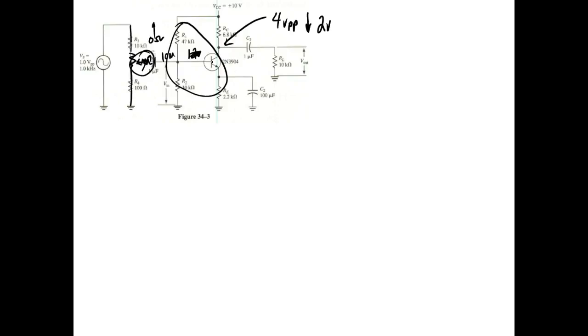But what I can do is adjust this till this drops down to 1/2. When that drops down to 1/2, I know that the rheostat equals the input impedance of the amplifier. Then what can I do? Well, I can turn it off and measure the value of my rheostat. So the value of my rheostat is going to equal the input impedance of the amplifier, right? Everybody understand that?